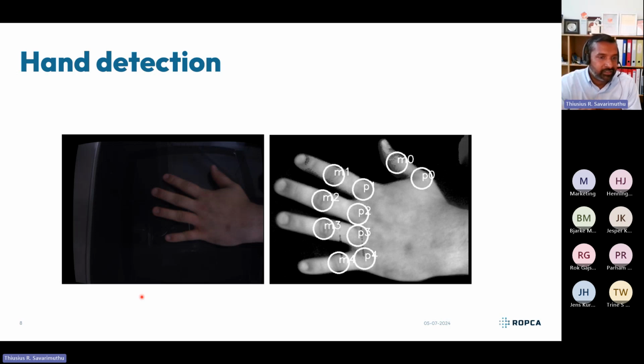So we created a good old-fashioned vision pipeline where, based on the image you see here on the left, we would come out with results showing where the joints of the fingers are that we were interested in scanning. And this vision pipeline was then the base for the first landing point for the scanning process, where the robot could then scan the patient.